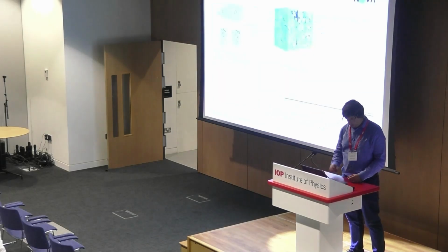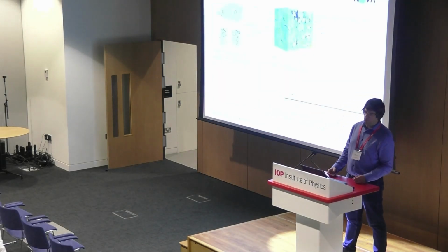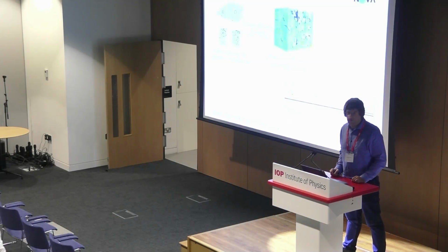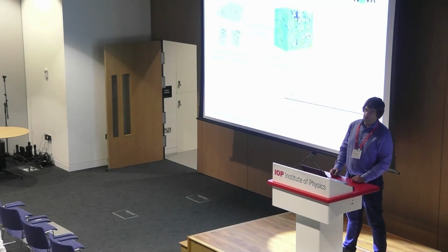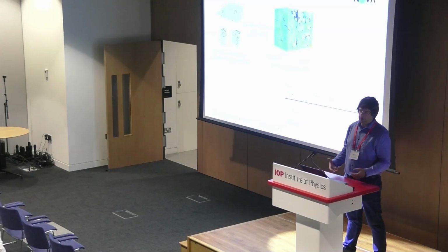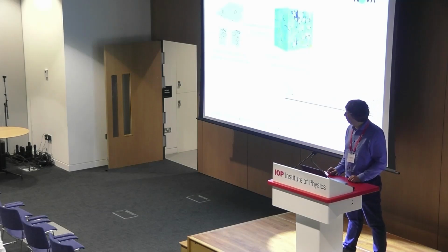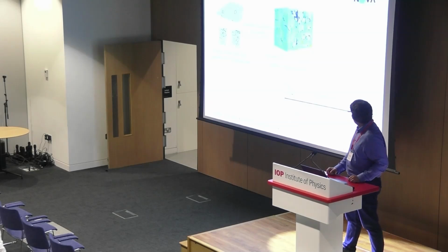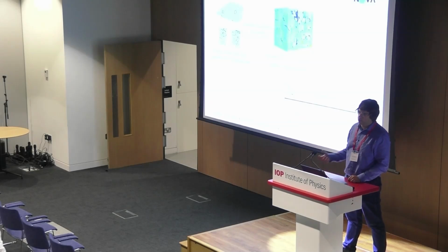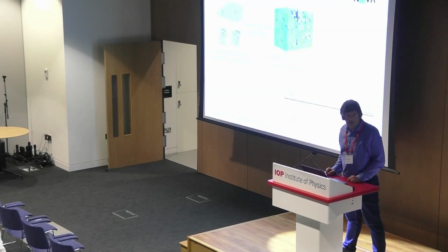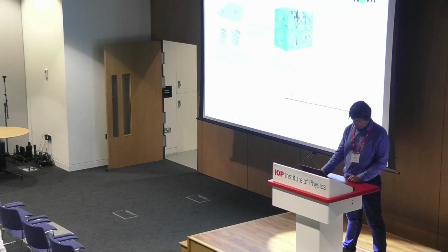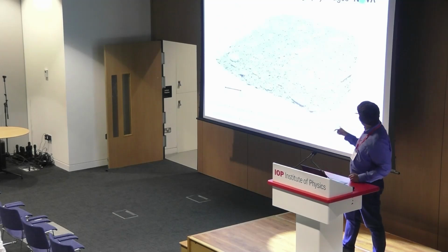So what we did was to obtain X-ray tomography images of our monolith, then we reconstructed its structure from those images, built the mesh, and after having the mesh, we performed CFD simulations with OpenFOAM in order to predict the flow patterns, tortuosity, and residence time distribution through our monolith. So this is the starting point from which we started to work.